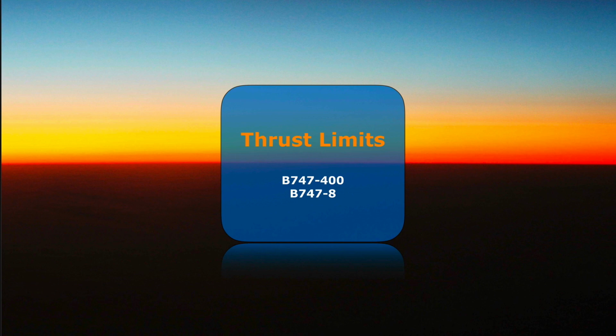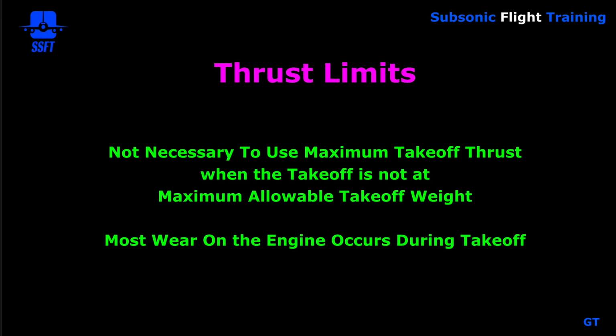Our briefing today will cover thrust limits of the 747-400 and 747-8. A lot of the time it's not necessary to use maximum takeoff thrust when the takeoff is not at the maximum allowable takeoff weight. So if we're at a weight that allows a reduction of thrust, we'll utilize that, because most of the wear on the engine occurs during takeoff.